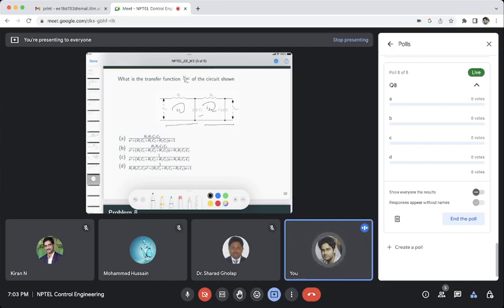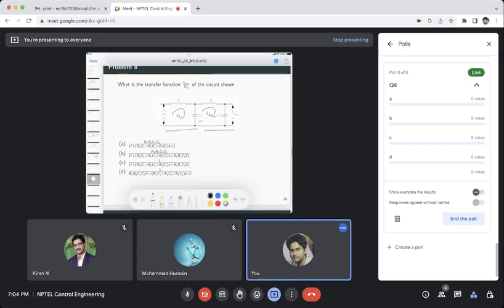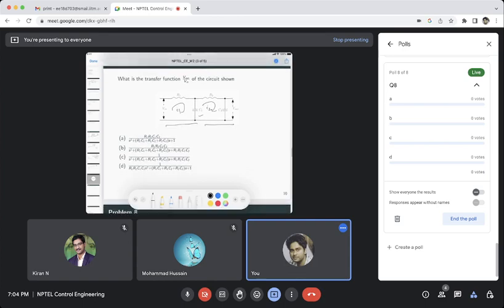If there is an amplifier present with unit gain, which avoids this loading effect, then there will be no loading effect, and you can simply apply the cascade formula. So just try this. Simply write KVL and then eliminate the currents that are not necessary. Then you will find the transfer function V out by V in. You can just work in the Laplace domain directly.